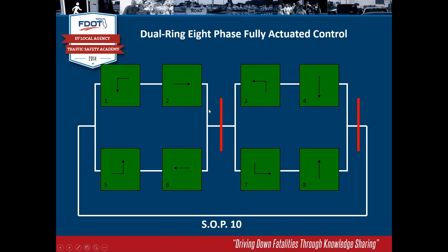And then as we get ready to cross the barrier, we said we had nothing southbound, but we had northbound lefts and throughs being detected, so we would then start up 3 and 8, because we would skip 7 since nobody detected there, and so we just start 3 and 8. And after they ran it for a little bit, we have nothing being detected for 4. So 3 and 8 run, and then we cross the barrier and start it over again. And so the next cycle could be something completely different.